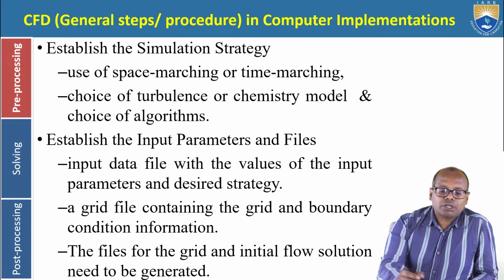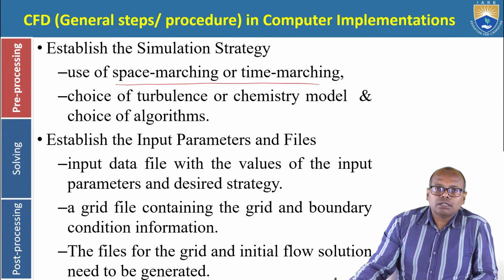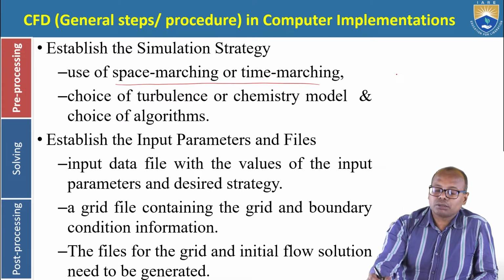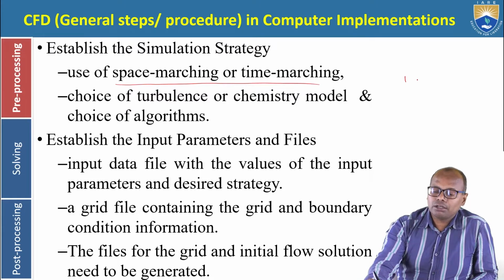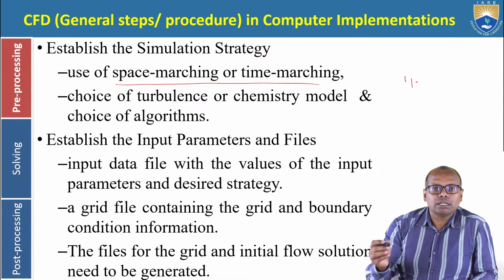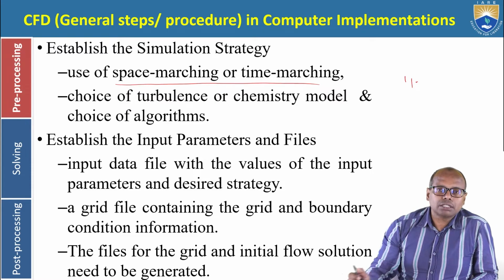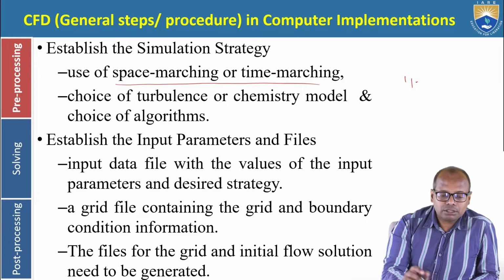Now what we have to see is how the space marching and time marching techniques are used inside the simulation. What should be the time gap between two iterations? Suppose 1/10 of a second, or 1/100th of a second, or 1,000th of a second. That is what we have to identify. And the space marching, this we also have to identify.